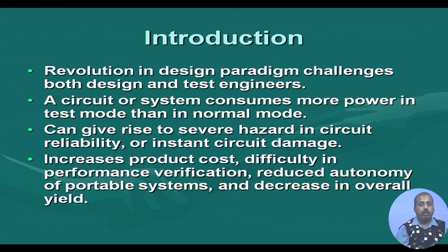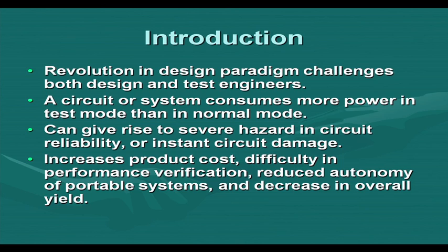So, if we want to do power-aware testing, then we have to take some special care. We may want to test a number of components together to speed up the testing process, but it may happen that the combined power consumption crosses the power limit. As a result, we want to restrict that. So, we cannot do that parallel testing. That way the testing time will increase, and that will affect the product cost.